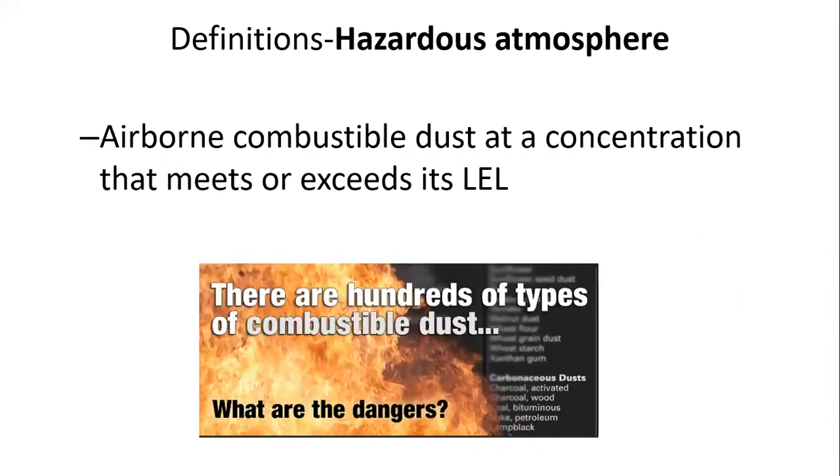Here's something I'm not sure you know, but dust can also be explosive. So we have to be careful, and this happens a lot in grain elevators and places like that, where you have a lot of dust, that dust can actually be combustible. So we have to watch out for that as well, because some of the spaces we're in could be pretty dusty. It doesn't have to be a sewer. It could be a confined space, maybe in an incinerator building where there's lots of ash and dust floating around.